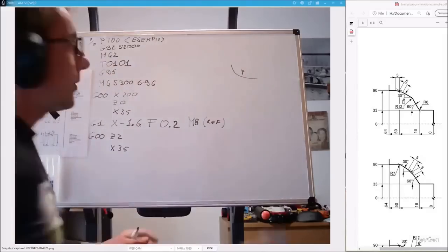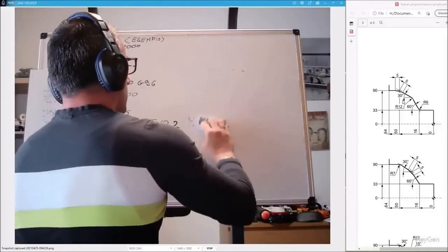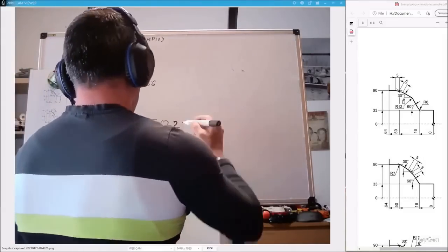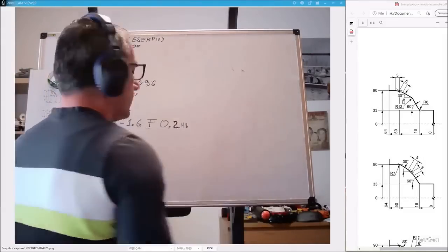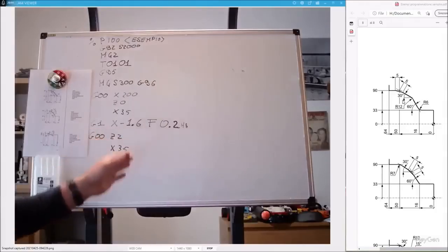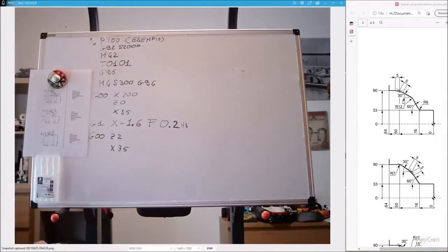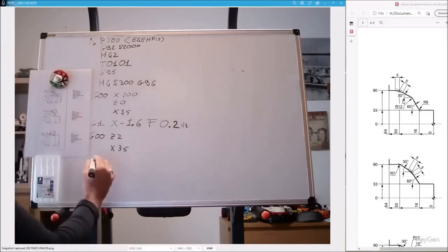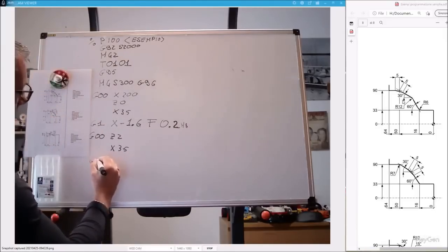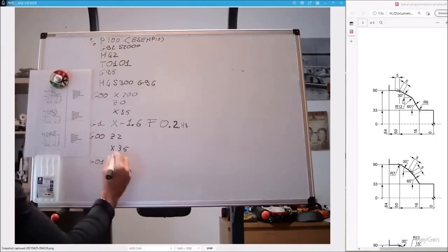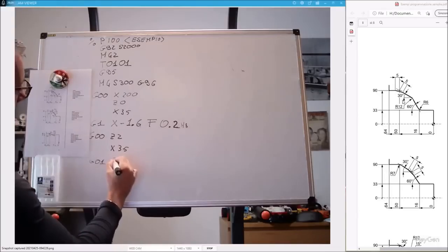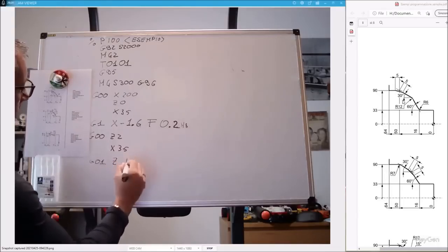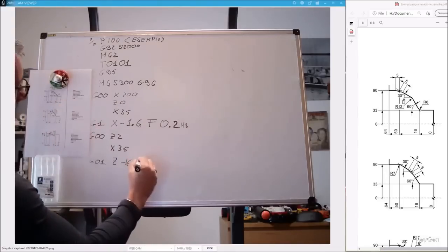I do this because I didn't take the spaces into account. So M8 for coolant: during rapid movements, I can decide whether to keep the coolant on or off. Well, I'm here, and I need to switch to G01. Go to Z16, ending with a radius of 6.